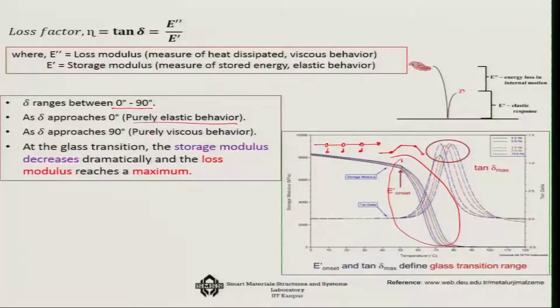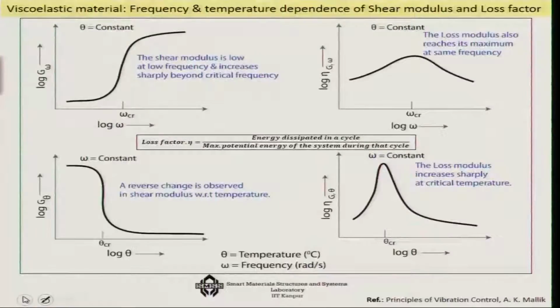So, you get a crank-like motion, and that means a lot of mobility comes into the polymer, and that is why such a sharp decline in the real modulus starts to take place. Because of this decline, a lot of energy is getting wasted, so you get a sharp peak in the loss modulus of the system. So, this is the material explanation of what happens to the system.